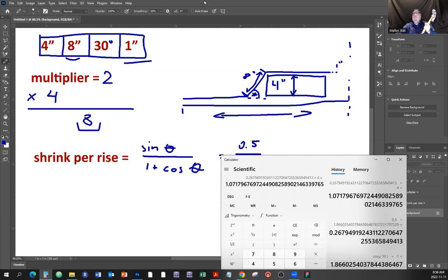Now I'm going to stop screen sharing for the last time here. All right, so this sticker says, let's say if we want to clear 5 inches, the distance between the bends is 7 inches if you use 45 degrees.